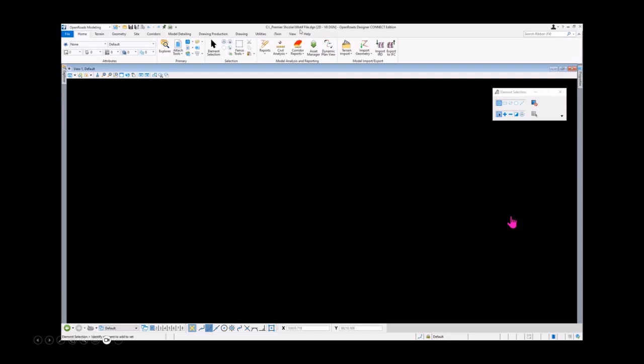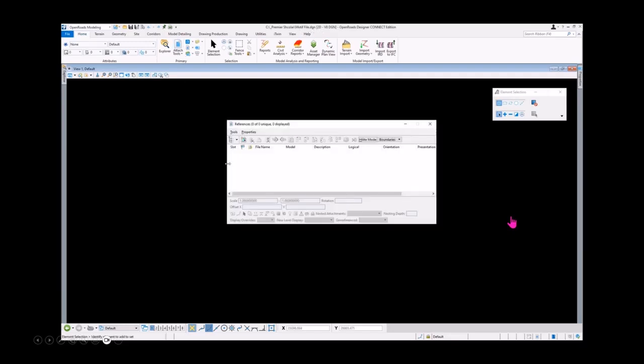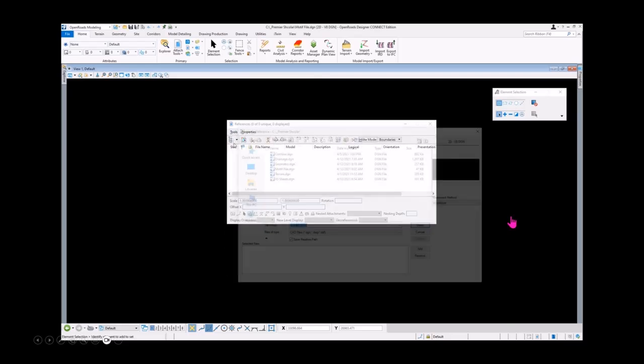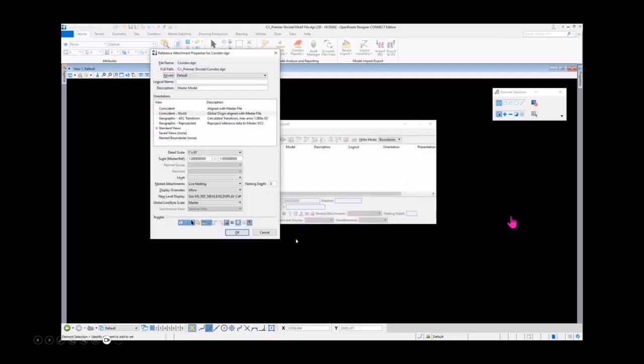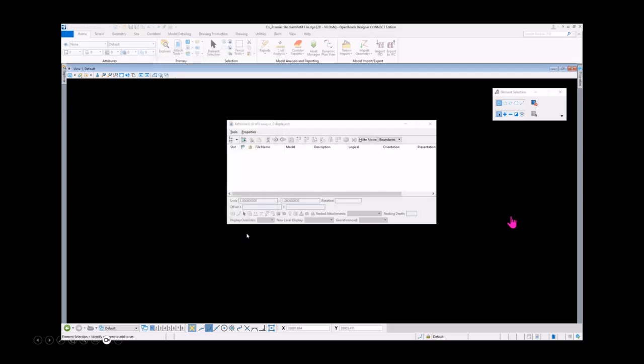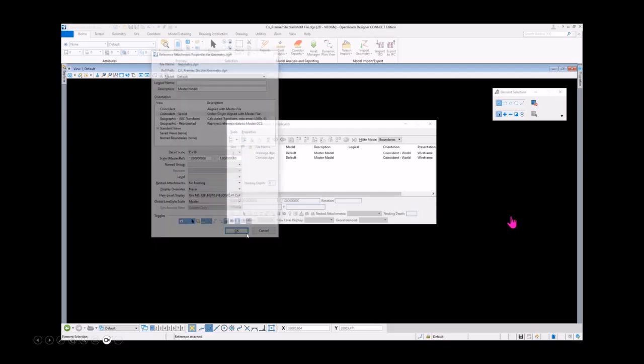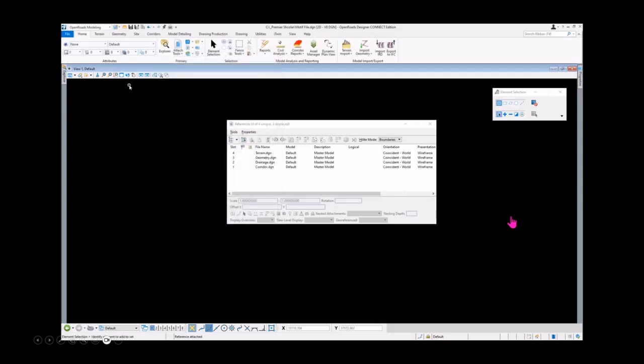And so we're going to create a name boundary file. One tool or tip we could say is you don't have to cut the sheets in the same file as the name boundary. You can just reference in what you want. This could also be done using reference containers. But in this case, I'm just going to do a direct attachment and say no nesting, and do that for all of the files that I chose.